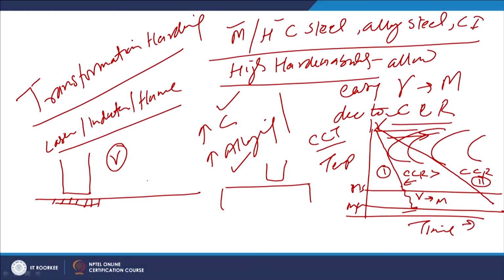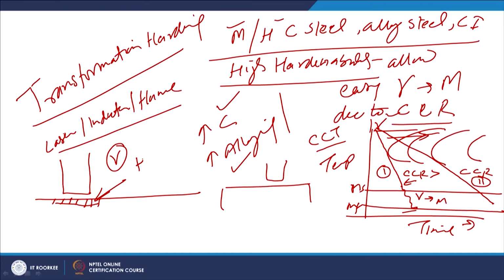As far as the heating is concerned, the heating temperature and the time at that temperature are important for the transformation of soft phases, which are normally present in steel in the form of pearlite and ferrite. These phases have to transform into austenite for the formation of homogeneous austenite.